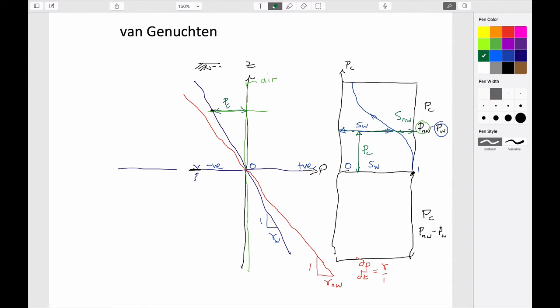So in other words, as you get further up the water table, originally it's fully saturated with water, you go up a bit, it's still fully saturated with water because it's the tension saturated zone. You keep on going up, you get progressively more and more air in the system, and the water becomes more and more scarce and less connected. So this is the mapping that does that. And I suppose the important thing to note is that the sign convention automatically takes care of this in terms of capillary pressures.